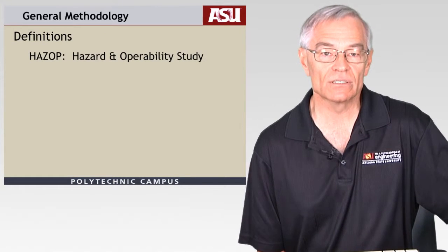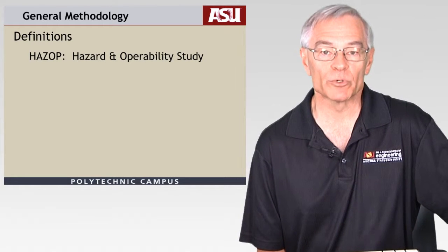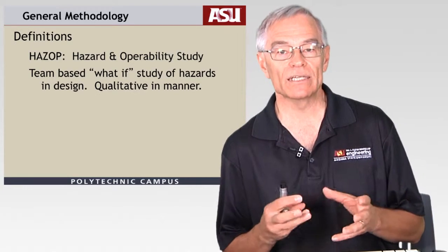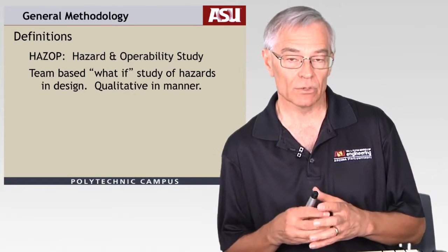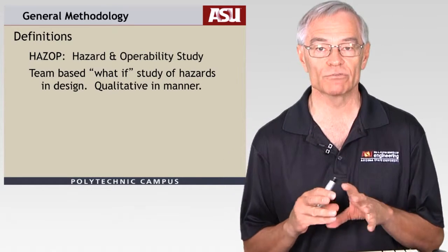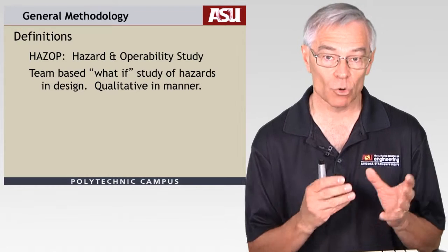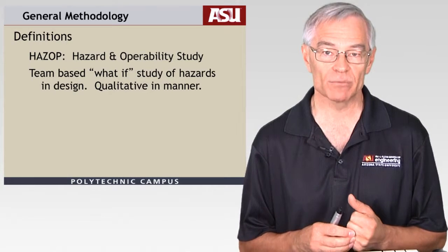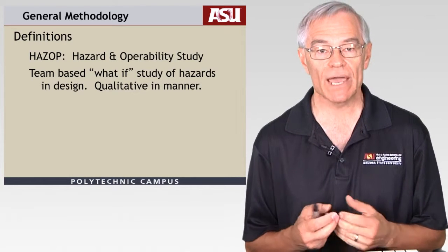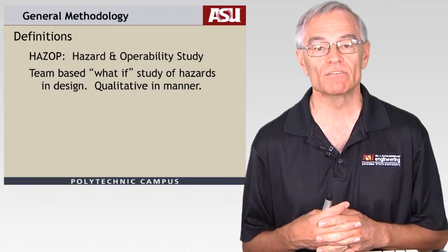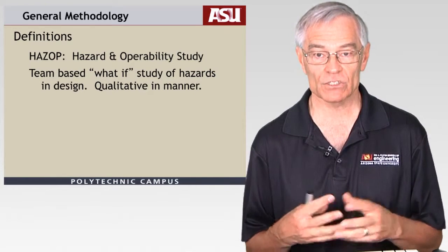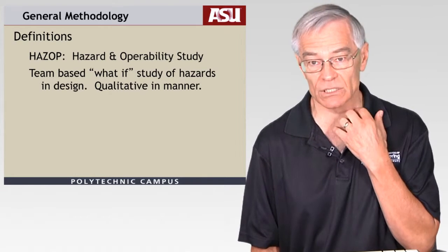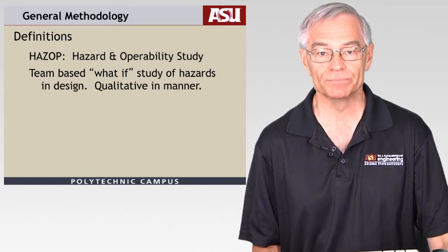So some definitions again. HAZOP is a hazard and operability study. So it primarily focuses on hazards in design or operation, operability. Think process industry. So often you're focused on various situations, what might go wrong, that hazard, and then what the effects of that might be and how to mitigate it. So a HAZOP tends to be a team-based study of those hazards and what you can do to fix the condition, so to speak, mitigate it. And usually it's qualitative in nature. Qualitative means, again, it may not be numbers driven.